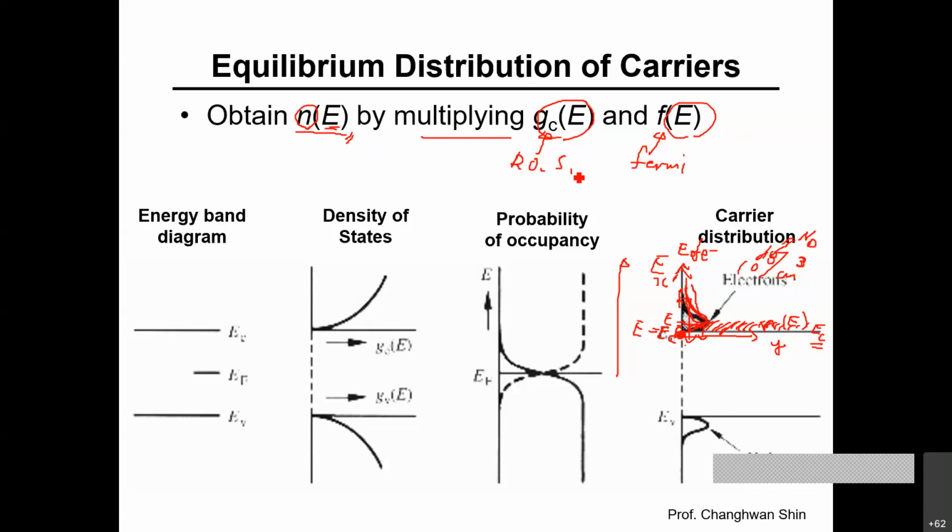Okay, going back to the silicon material. We know the Fermi function and we know the density of states in the conduction band. Now we are almost geared up with the density of states and the Fermi function to look for the electron concentration, n(E), as a function of energy. So let's take a look at the details on the bottom side.